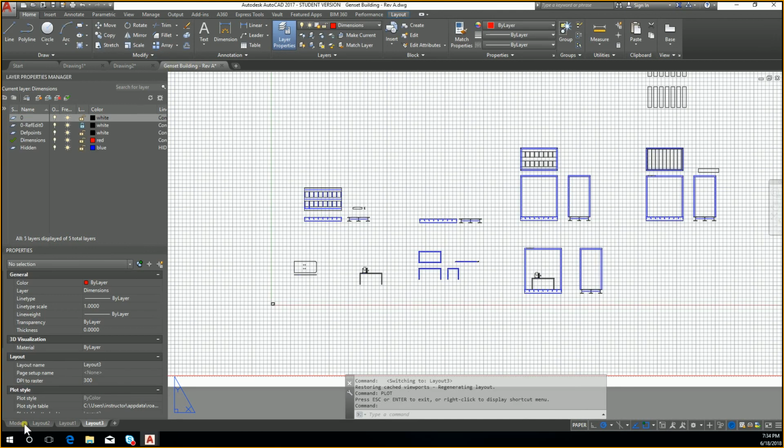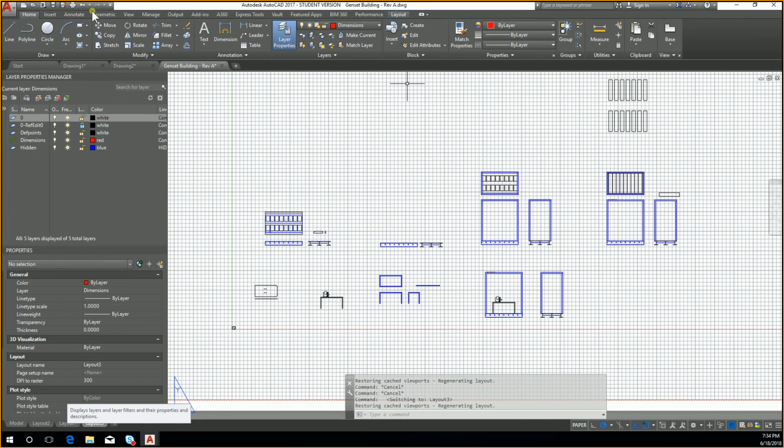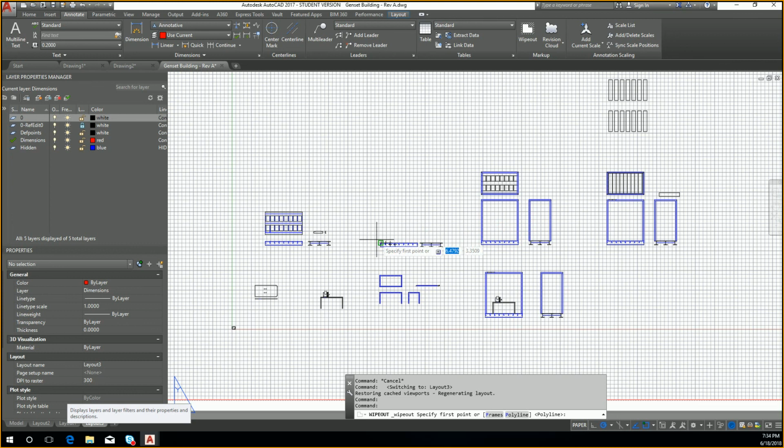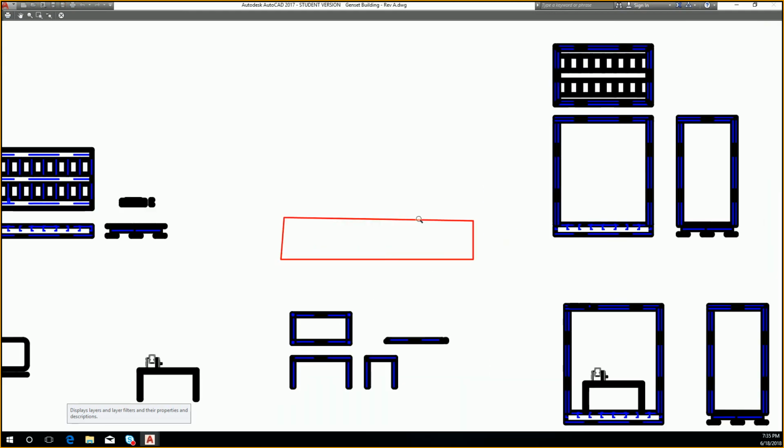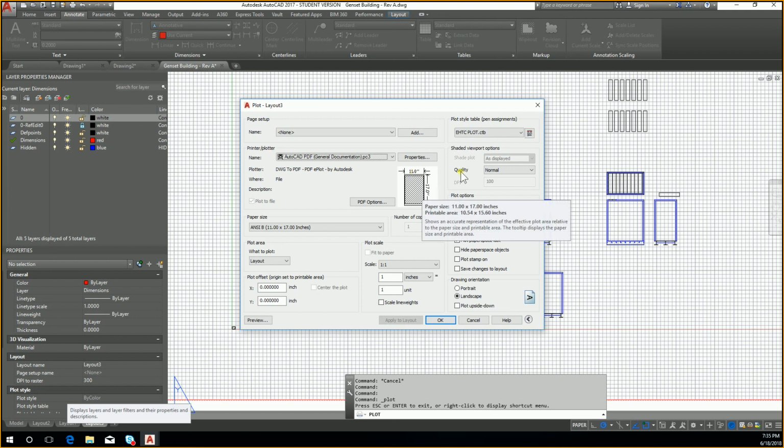And getting back to what we were talking about with the redact. So let's say I'm just going to redact something here. Annotate. So let's say for whatever reason I want to hide that one view. When I go to plot, that's gone now. And there's no way to remove a redacted section, or sorry, wipeout in AutoCAD. But essentially that's redacting the information on your drawing package. So if you need to hide something, that is how you would do it.